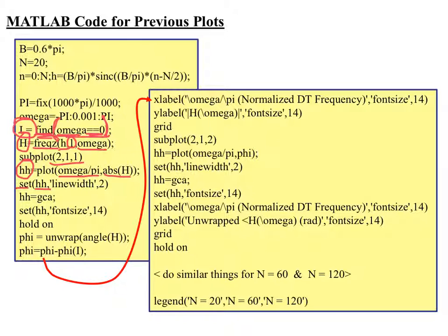In this case, I find that when I make plots, the line width is so narrow that when you import them into PowerPoint or Microsoft Word for publication, the line widths are so narrow they don't really show up well in the PowerPoint or in the Word document. So I tend to automatically just go right to line width 2. That sets the line width, so I get a little thicker line on my plot.